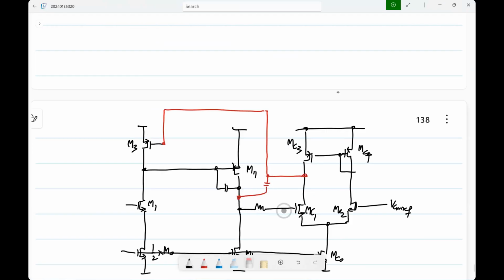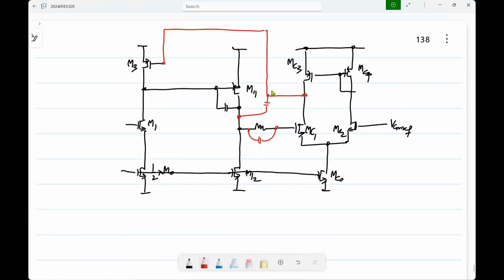And of course, if this resistor is very large, you will have another parasitic pole there. And to fix that situation, you may need another capacitor there. Okay. So if you have three stages with high gains, this is what you will have to do. Okay. Now, why would you use three stages normally? What's the reason for going for three gain stages? To get very high gain. Now, that may or may not be required for the common mode feedback loop, such a high gain, right?